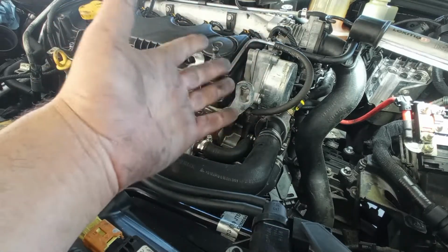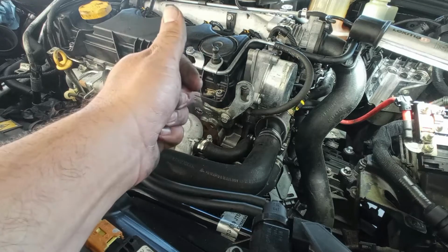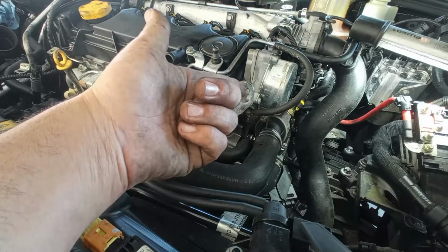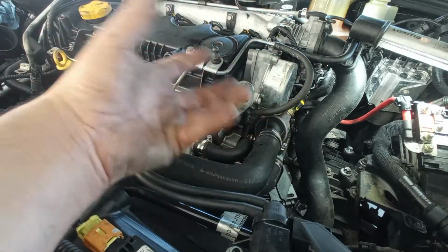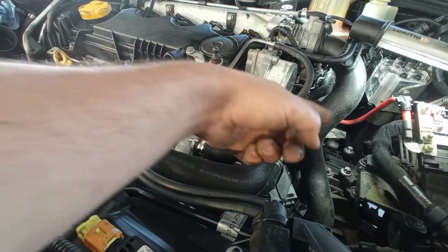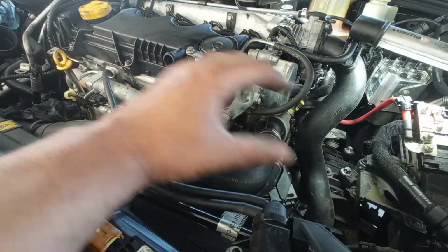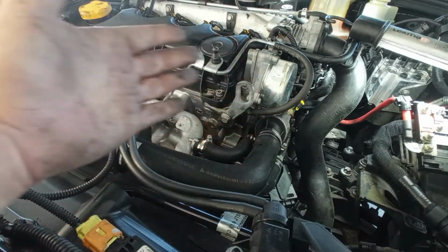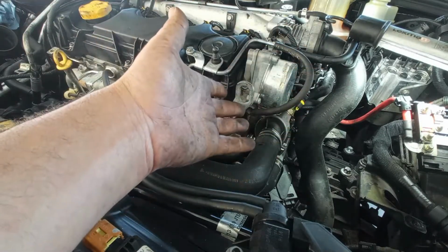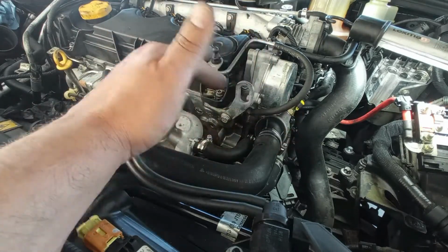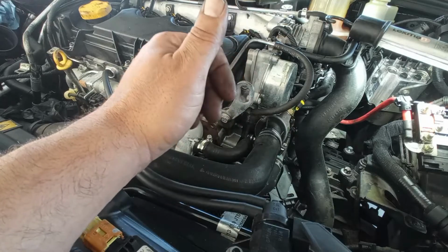But you can separate this into two things. Control of air, separating into parts: quantity of air and pressure of air. Everything that involves intake of air, you have to control very, very well. Being vacuum, pressure, intake, EGR, whatever, you have to control everything. Exhaust also makes part of the passageways of the air, because if the air enters the engine, it has to leave the engine too, okay? So the entire exhaust system, having DPF or not, it is the same thing. So the entire exhaust system also has to be verified, okay?